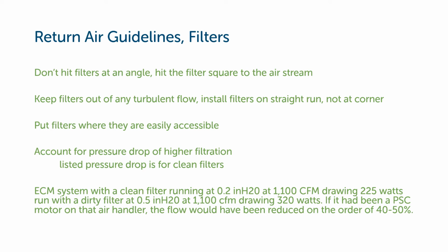With PSC motors, permanent split capacitor motors, the air handler flow would be reduced. It doesn't have the capacity. It feels that pressure, and if it feels too much static pressure, it just ramps down. In that case, we might use a little less energy, but we're going to move a lot less air, in the magnitude of 40 to 50% less air. So if we're not moving the right amount of CFM to the room, what's the point?